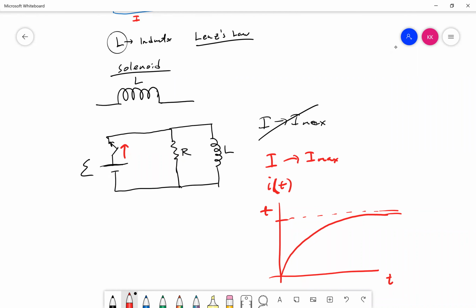That means we're going to be exploring a circuit in which, by introducing the inductor, where L is the inductance of the inductor, we're introducing a device that allows us to control the current. For example, if there is some sudden spike in current that can be dangerous to the circuitry, the inductor can prevent that by slowing down the rate at which the current is increasing.